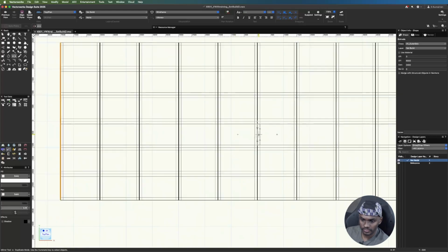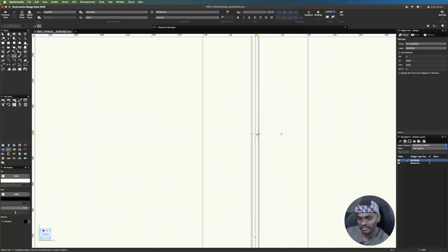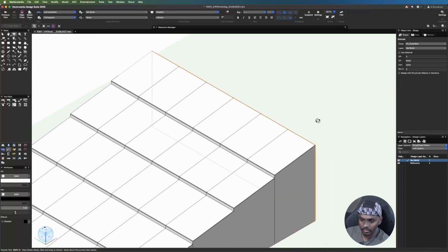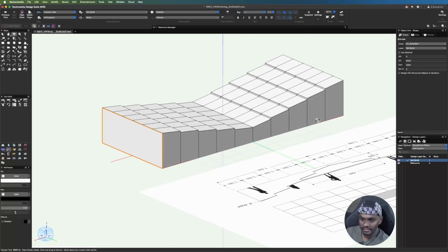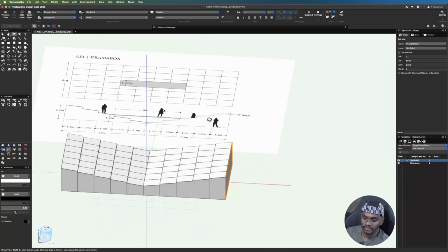And there we go. So since I have my outer frames in place over here, I want to select them all and then go into my top plane. And using my mirror tool, I want to mirror them on my mirror line to cover the front.